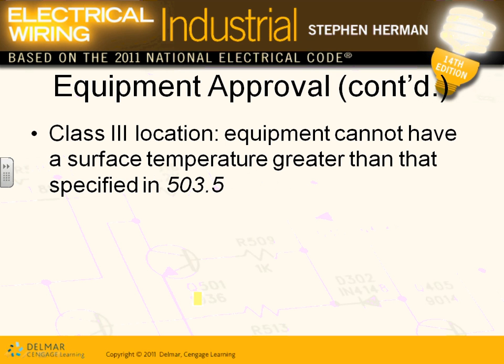Outside temperature, same thing in Class 3 locations. The most important thing when you put in a piece of equipment is that it does not have a temperature greater than what's listed in 503.5.